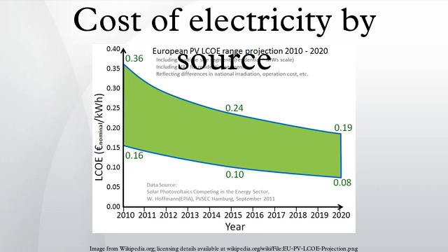Total system levelized cost gives the dollar cost per megawatt hour that must be charged over time in order to pay for the total cost. These calculations reflect an adjustment to account for the high level of carbon dioxide produced by coal plants. From the EIA report, a 3 percentage point increase in the cost of capital is added when evaluating investments in greenhouse gas-intensive technologies like coal-fired power and coal-to-liquids plants without carbon control and sequestration.